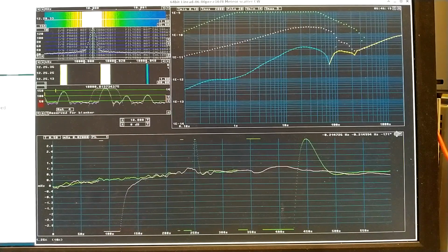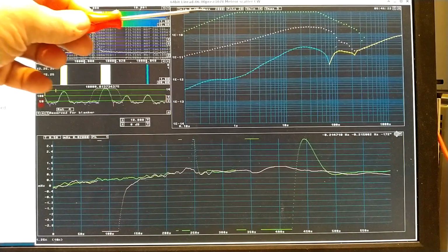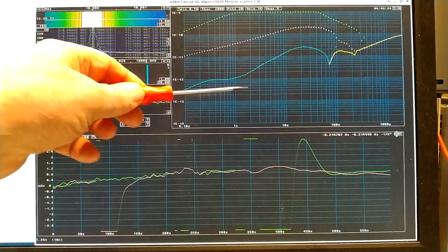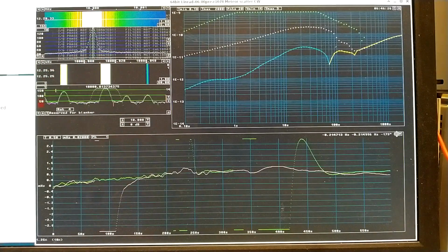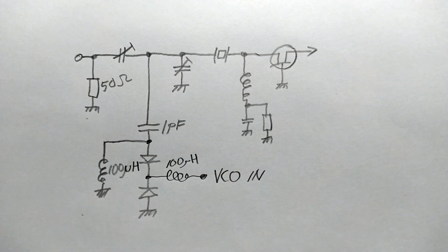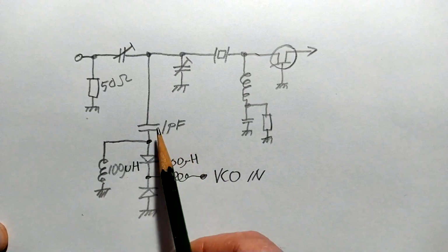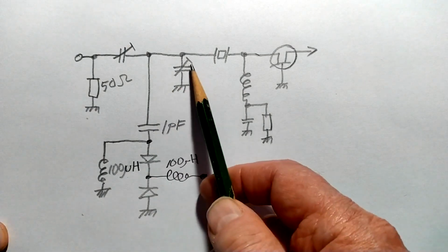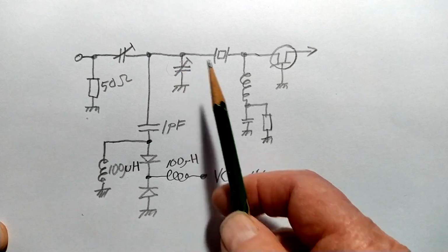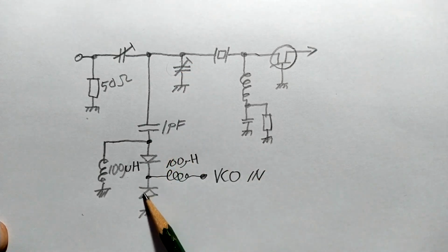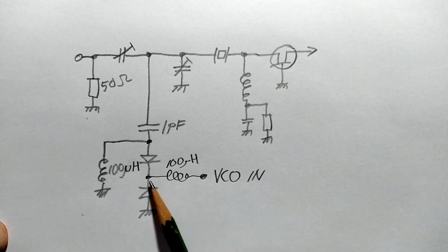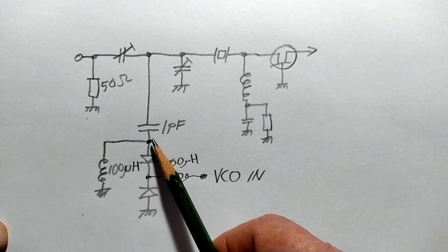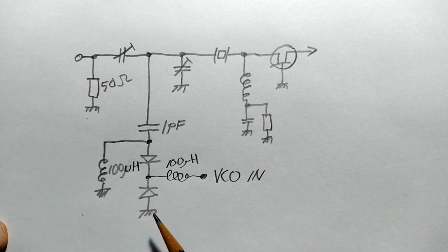The large frequency jumps have of course destroyed the Allan variation completely up here, but that's not what I'm interested in for the moment. This is the frequency control circuitry. A 1 pF capacitor connected to the tuning capacitor here, and then 2 series connected varicaps, and the VCO input here, and this gives the tuning range I had of channel 2, which was the first I had made.